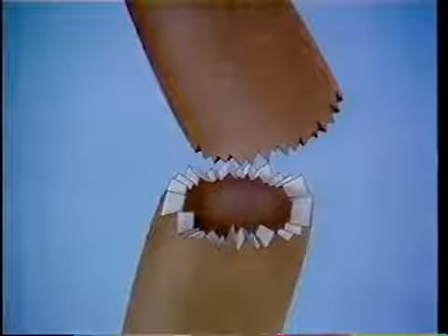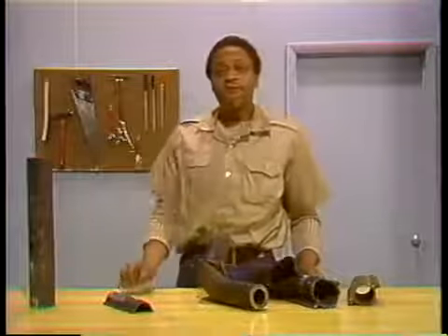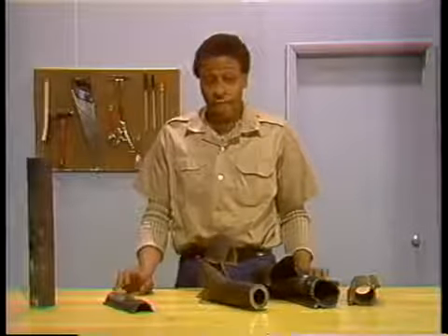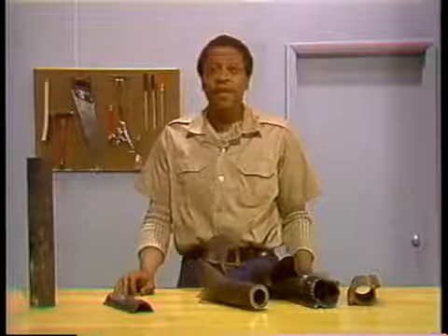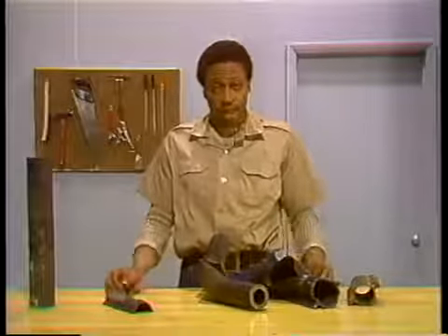Double-end ruptures are also caused by overheating. Here, the tube separates completely at the point of failure, leaving two free ends. Three more failures you may run across are fatigue cracks, tearing of tube metal at weld patches, and the tearing of tube metal at support clip attachments.